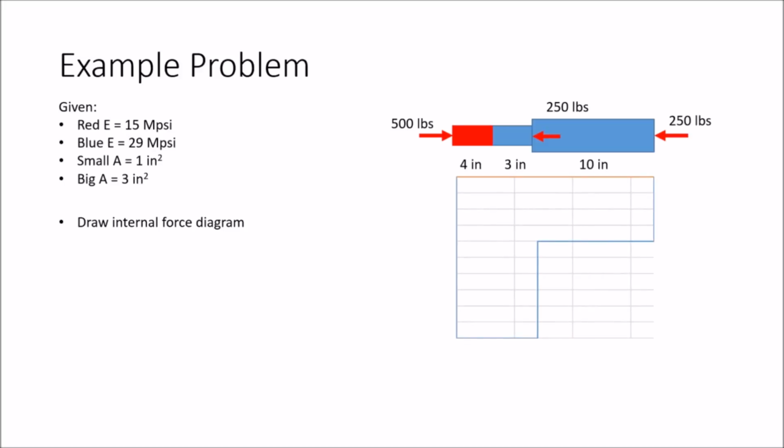Finally, we need to make a deflection equation for each change in cross-section, material, and internal loading, which means here and here. Since the change in cross-section and the internal loading are at the same point, we can combine those two equations into one equation. Meaning we don't need one equation for the change in cross-section and one for the change in internal loading. They will be the same for each.